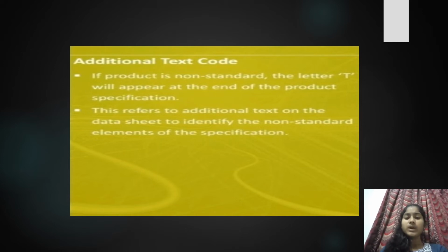In this way, the drift can be considerably reduced, although the performance of a VCXO is still not as good as a full oven controlled crystal oscillator. It is able to provide a level of performance better than that of a single uncompensated crystal oscillator and for much less than the cost of a full oven controlled oscillator.